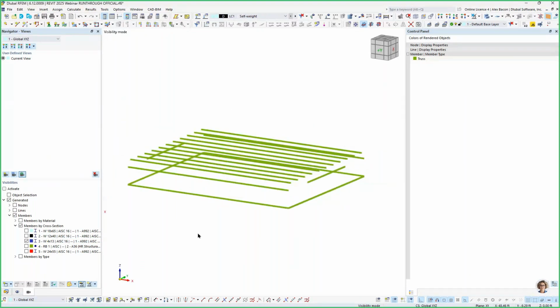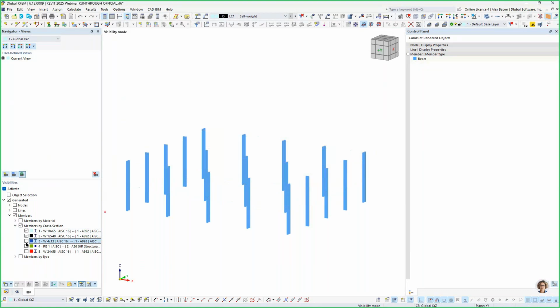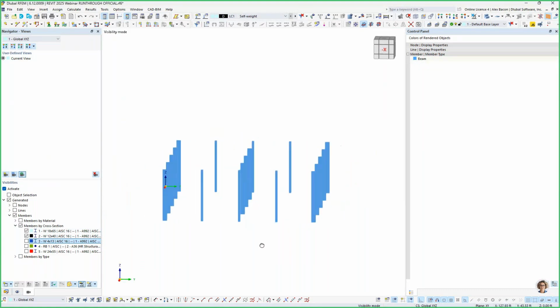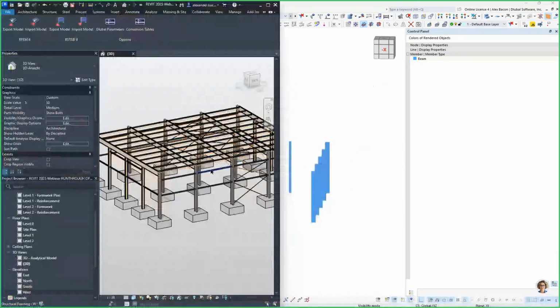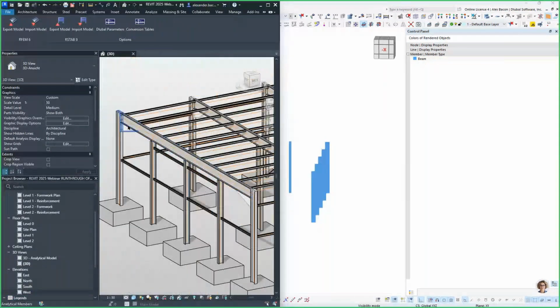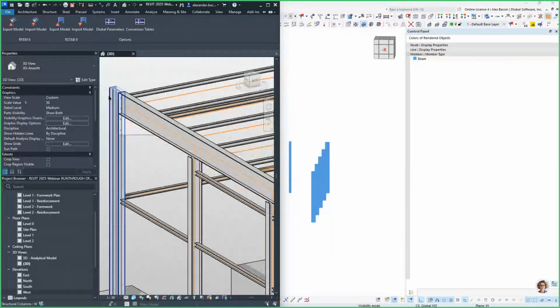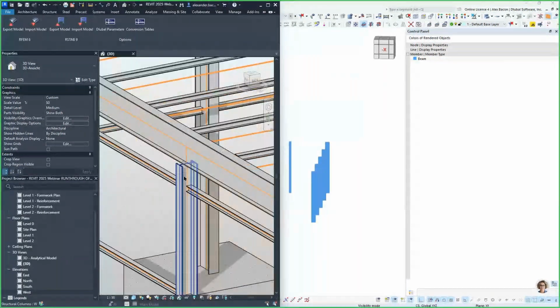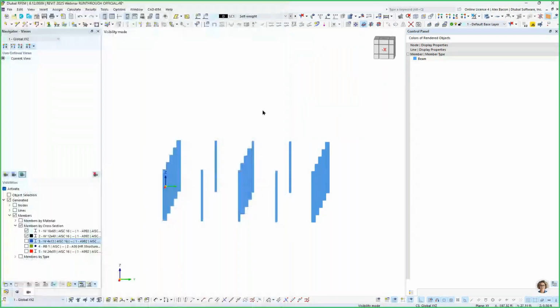And now lastly, I would also like to apply hinges to my wall and center columns. So I will create or show those. I would only like to apply some member hinges since we have pin connections here at the top of my columns. I just realized I forgot to mention the connections. Yes, I have some connections defined in Revit. So for the columns and beams, I have some plates and fasteners, and then the columns framing into the beams here are pin connections. So I'd like to consider that in RFEM.